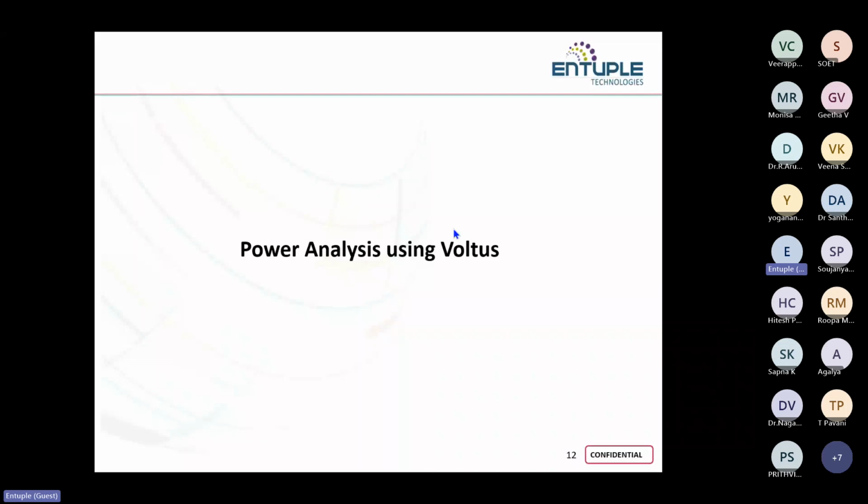And so in all the phases, like RTL code also, nowadays tools are there to estimate power. Normally real values will come only at post-route power consumption, but people have been estimating at the RTL code itself, and then at every stage simulating using VCD, changing switching activity of your standard cells and calculating switching power, estimated power there also. And then after synthesis, in the synthesis stage also, you will get the overall power report.